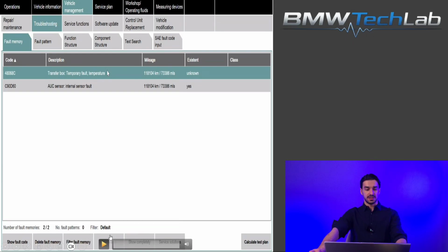And this is typical for this car, because if you have experience working on these modules, you know that it's very common for these cars to have problems in the transfer box. I already caught a lot of them with problems in the transfer box, but normally the problem is not the four-wheel blocking. Normally the customer complains about some noises, some vibrations when he tries to increase the power from the engine or to get the maximum power from the car. This was quite different, because this car was completely blocking the four wheels when we tried to drive it.